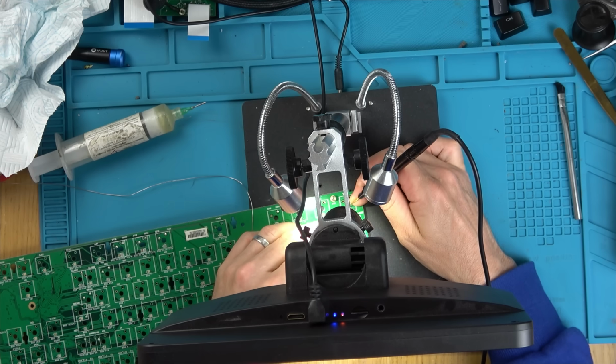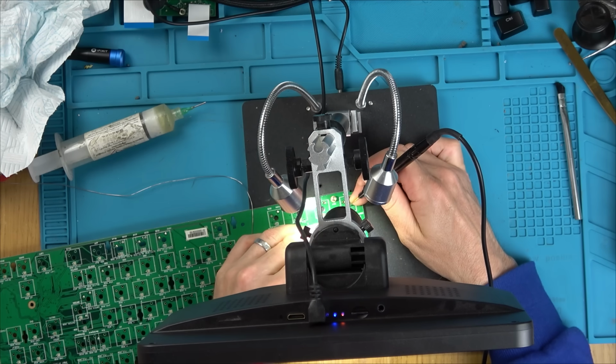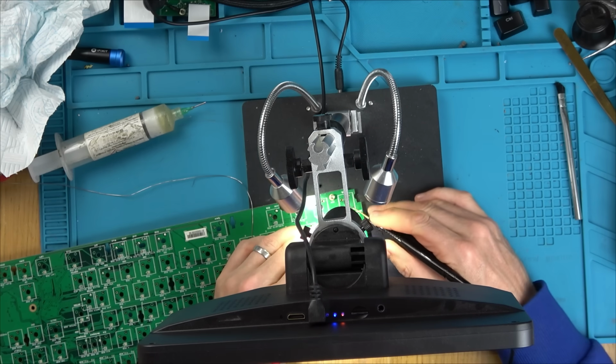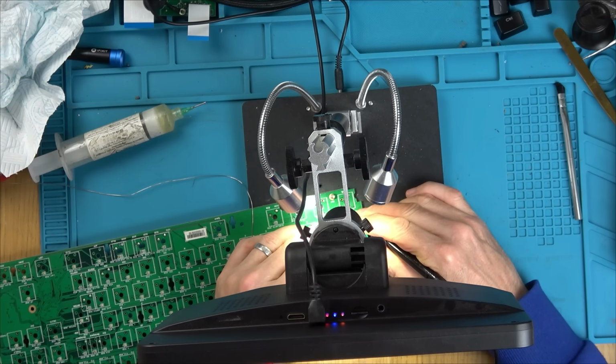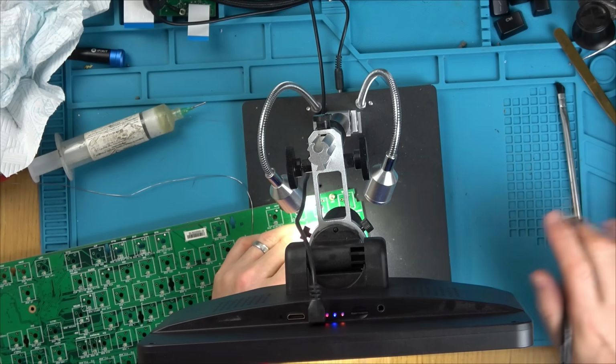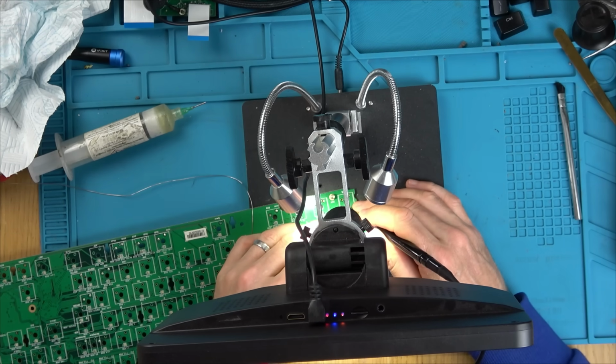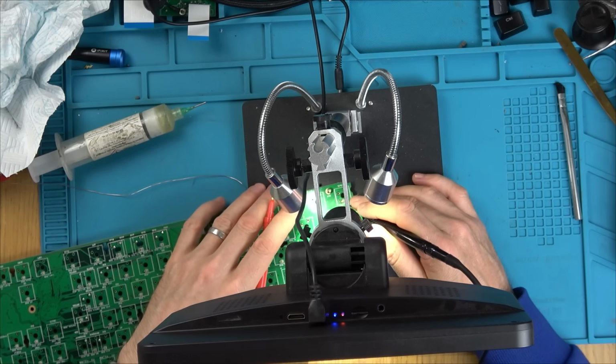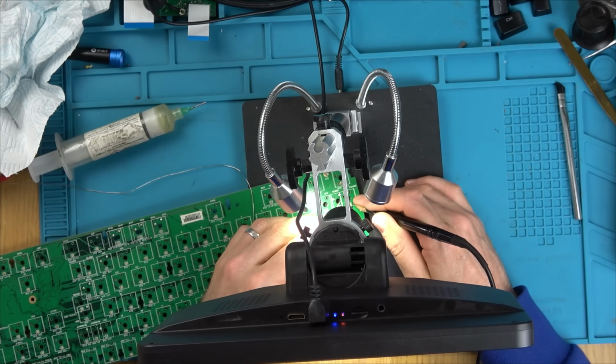So let me show you a bit of footage now from just a top camera filming the microscope that you can't see, and then I'm actually going to show you some microscope footage which is more interesting, of showing you the different colours on the bench power supply, what a working LED looks like and what these failed LEDs look like. So it looks like it's not a trace problem, it looks like water has actually damaged the LEDs themselves, and that's why they're not working. No, what a shame. The LED itself's gone.